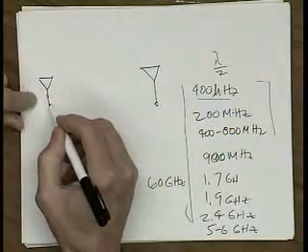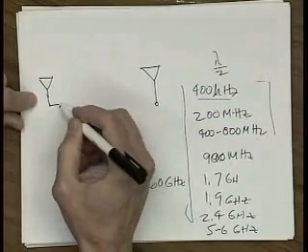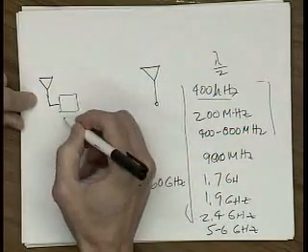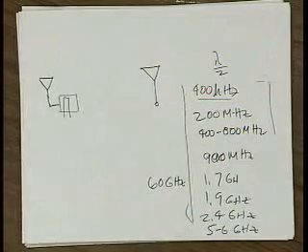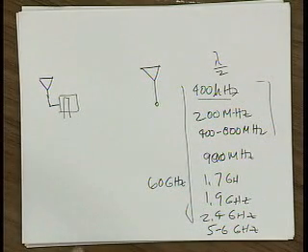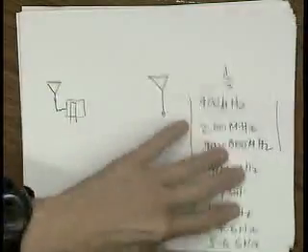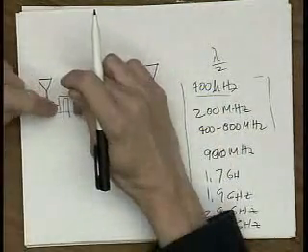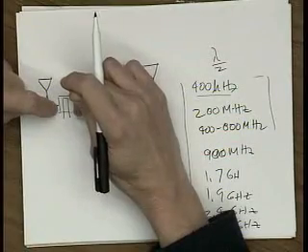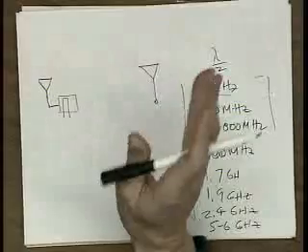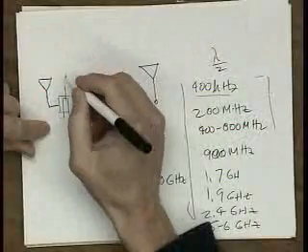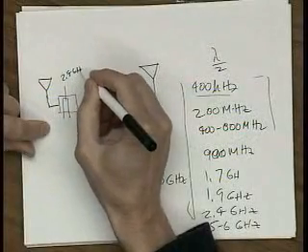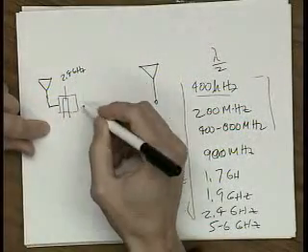The first thing the receiver usually does is go through a filter, because you're receiving everything in the world. When you stick this little antenna up, it's tuned for one frequency, but you don't want to receive all the other junk being transmitted. So you put a filter right off the bat, usually a passive filter, that gets rid of other frequencies besides the ones you want. Let's talk about a Wi-Fi system at 2.4 gigahertz, so it's centered around 2.4 gigahertz.